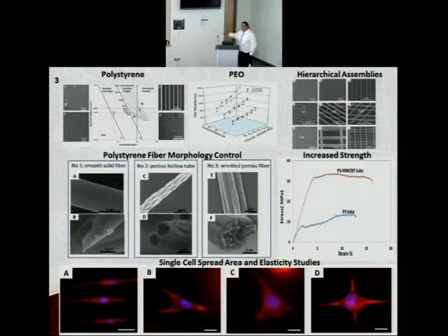If you have a molecular weight of polystyrene, say 1 million, and you want to deposit a fiber diameter of, say, 100 nanometers, what is the design space that you need to choose? You can come across the 100 nanometer line and intersect it with the 1 million molecular weight, go down on that, and that gives you the solution concentration required to form a 100 nanometer diameter fiber for 1 million molecular weight polystyrene. So this is a very powerful tool. This is not there currently in any of the polymer journals or polymer literature. By just looking at the chart, you can explore the design space.